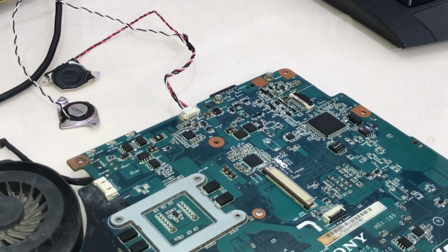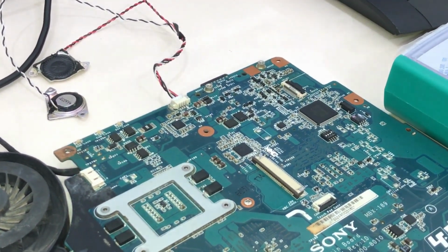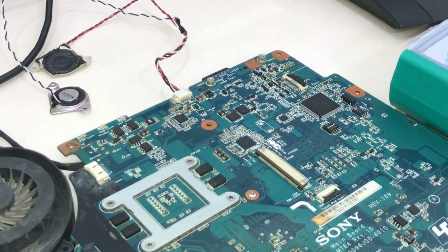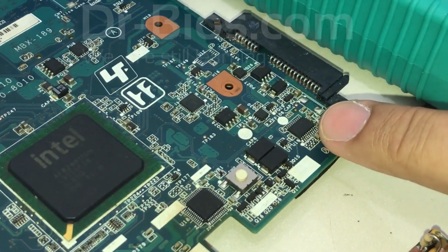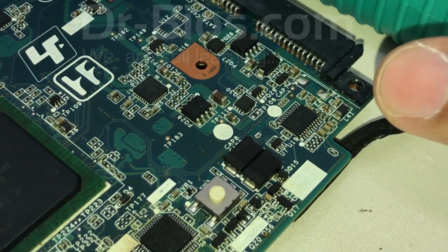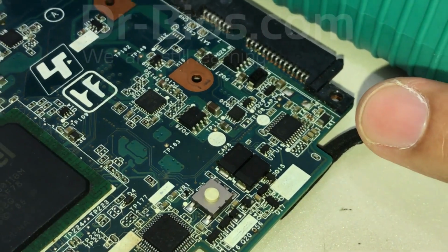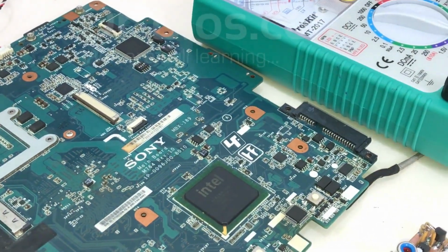Let me show it in the schematic as well. We could test it this way as well. We can test the speaker and its direction on the PCB from the amplifier output, by placing a probe on a pin and connecting and disconnecting the other probe. Now I show you the schematic.